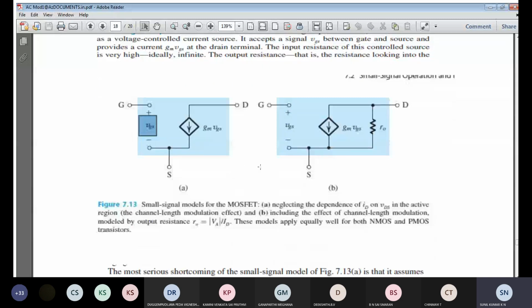In the MOSFET, whenever it operates in the saturation region, there are secondary effects and so on. When you realize the MOSFET at the deep micron as well as submicron level, the saturation equations are not going to hold good.